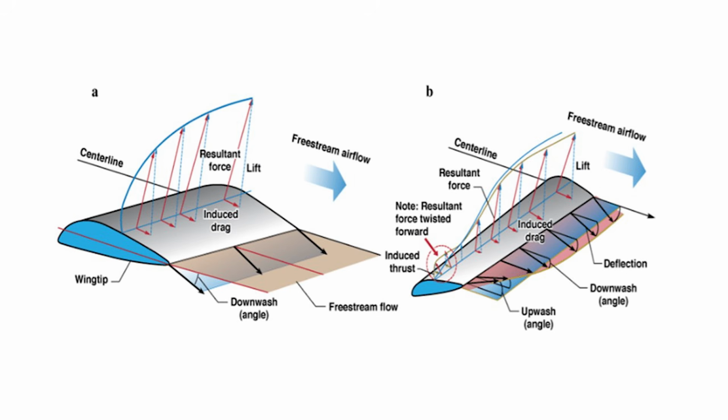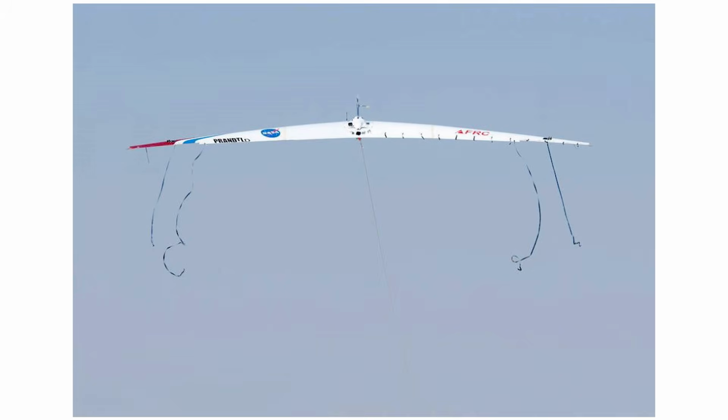And when an aileron or elevon is depressed for a roll control, it deflects downwards into upwash, reducing drag and producing proverse yaw. Normally, a downside aileron is in downwash, increasing drag and adverse yaw. This also means that you can retain roll control during and after a stall event, and this greatly reduces spin tendencies via the unloaded wingtips. This induced thrust helps to achieve proverse yaw, and it was proven in 2015 by aerodynamicist Al Bowers.